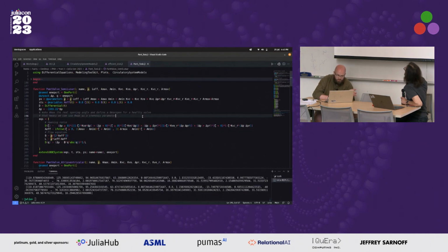With the functions from Modelling Toolkit, we can write it in terms of these Booleans, in that if the pressure difference is greater than 0, we've got the perfect opening. There's two ways to get these if-else statements in there. One is with Boolean operators, like this, which I personally find easier to parse than if-else statements. If you prefer if-else statements, they are interchangeable. The Modelling Toolkit if-else is symbolic and translates through completely.